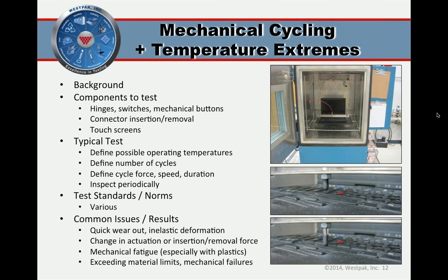So that's all done at room temperature very commonly, but it's also a good idea to combine this with extreme operating temperatures. So with our laptop, it could be used climbing Mount Everest, it's mighty cold outside, or on a very, very warm day outdoors somewhere in a desert. Will everything act as it should over a long number of cycles in those extreme environments? And this test will allow you to ensure that.